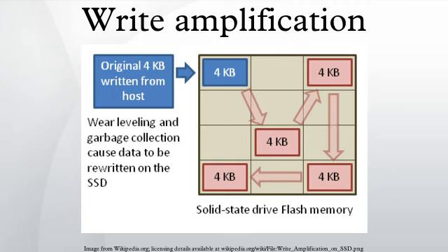The drawback to this process is that somehow the SSD controller must still find a way to wear level the static data, because those blocks that never change will not get a chance to be written to their maximum PE cycles. Sequential writes. When an SSD is writing data sequentially, the write amplification is equal to 1, meaning there is